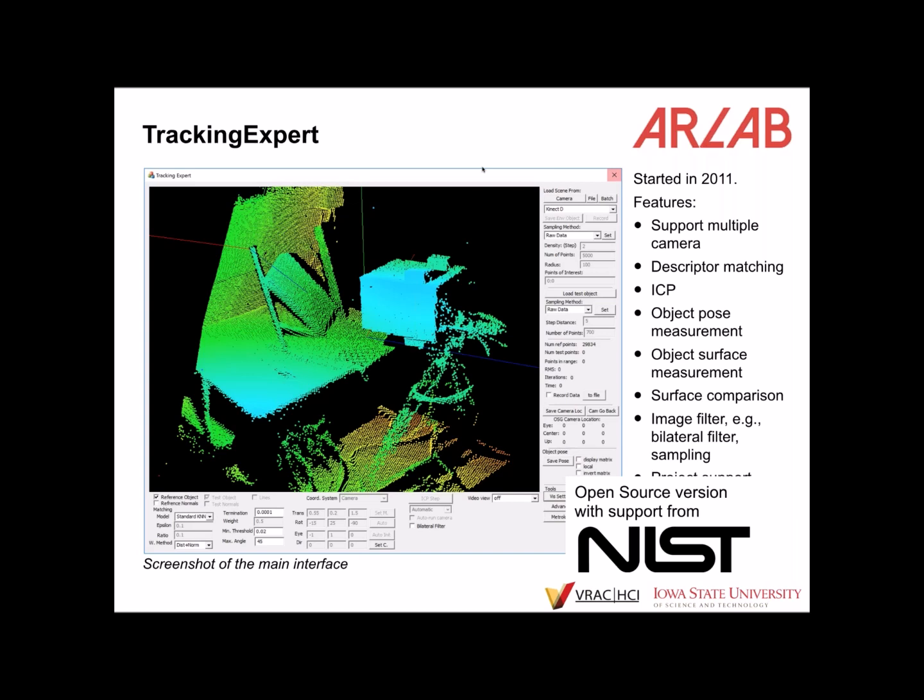Yes and no. We work mostly with RGBD camera techniques. From the first HoloLens, we did not really get an appropriate point cloud to do anything, so we didn't really use the data other than for testing. So what we did is we attached other cameras. This is a Structure Sensor camera, for instance, and other RGBD depth cameras on top of the HoloLens, or we built a mount for a Microsoft tablet and just plugged it into the tablet and used it on that. So these are the mobile devices that we use for that.